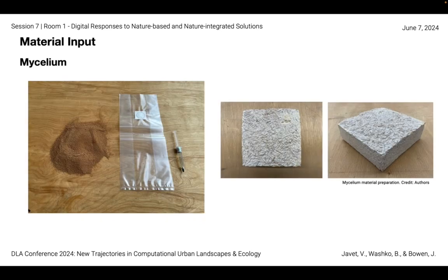Mycelium is a thread-like network of fungal cells, which has gained significant attention as an innovative and sustainable alternative to traditional packaging and insulation materials. Mycelium-based materials are not only renewable and biodegradable, but also lightweight, making them a valuable choice for testing as an eco-conscious alternative. A hemp-based growing kit was used, and the stalk was dehydrated at 150 degrees Fahrenheit, 82 degrees Celsius, for 5 hours.